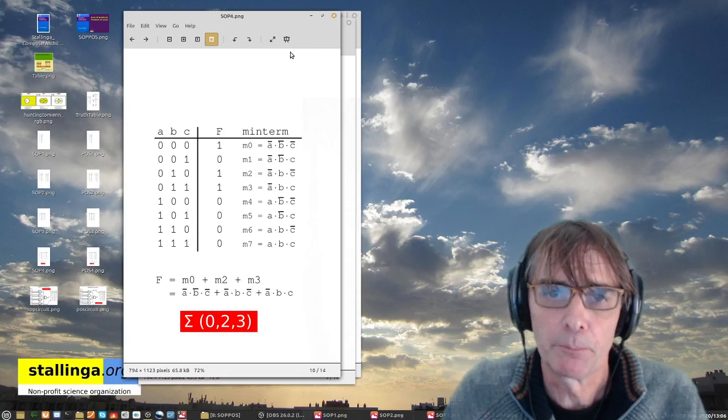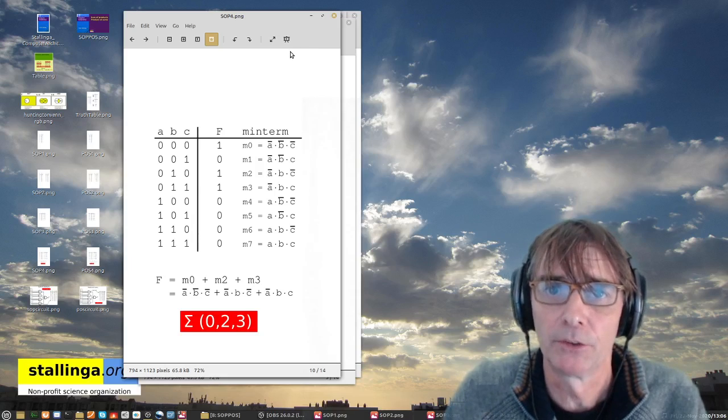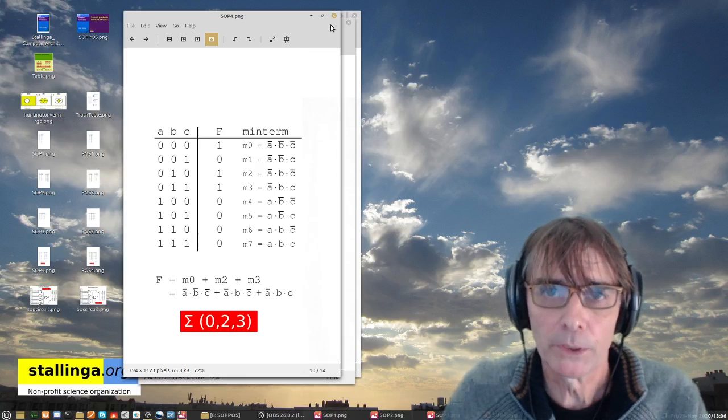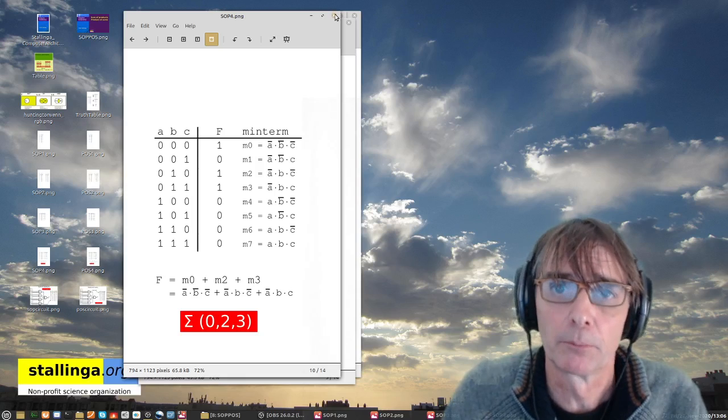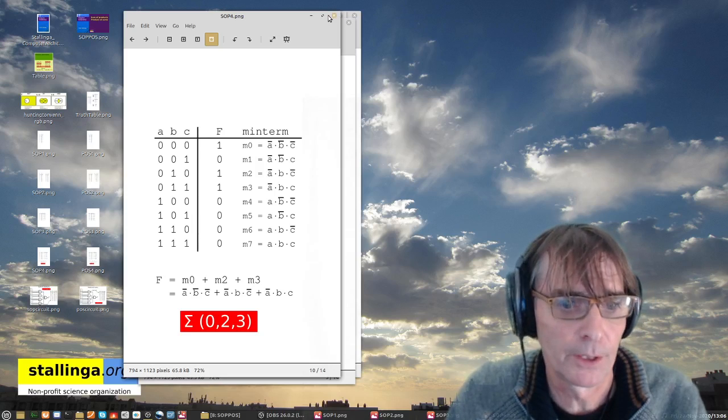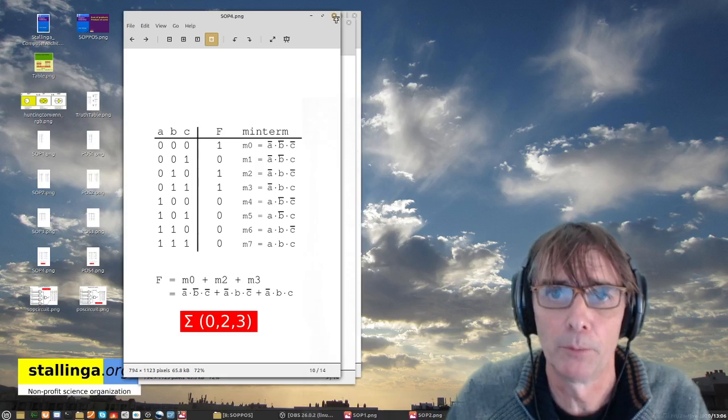On top, we can also simplify it by converting AND gates and OR gates to NAND gates and NOR gates, which actually also makes the circuit simpler, because as we will see, AND gates and OR gates have more transistors than NAND gates and NOR gates. That's for later in a moment.